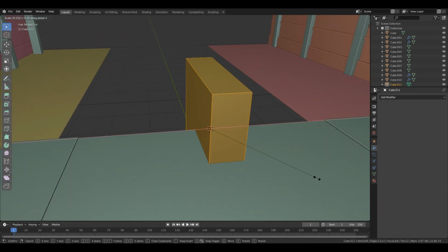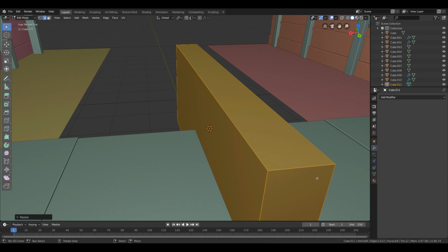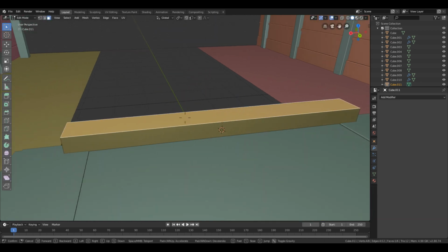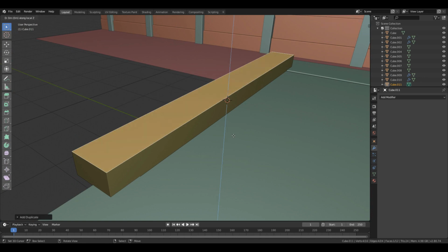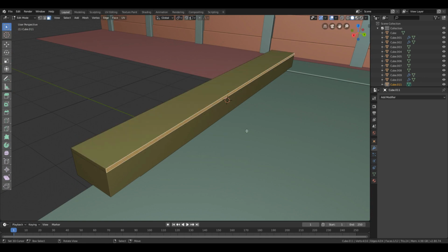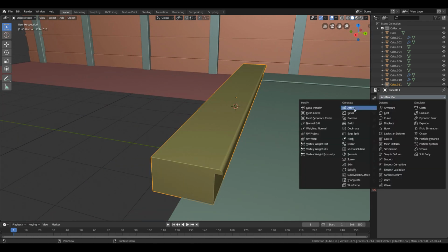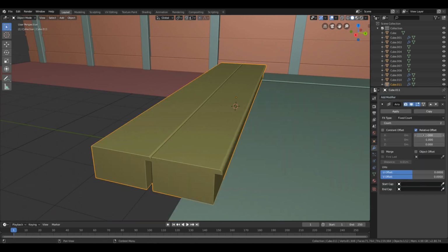After that, I made stairs with the x value of 0.25, y 2.5 and z value 0.13. Then duplicate the upper part of the stair face and extrude it slightly and pull it from front to cover the lower part. Then use array modifier to duplicate and position it in inclined direction.